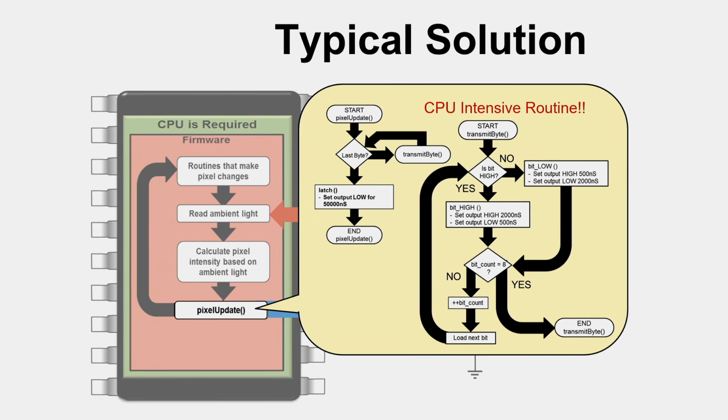That means by driving just one LED, you're consuming the full power of your CPU, the full resource. You cannot do anything else. Never mind 8 by 32, or the 4x4, it's like 16 times 24 bits of data you need to transmit at one time. And that's a lot.